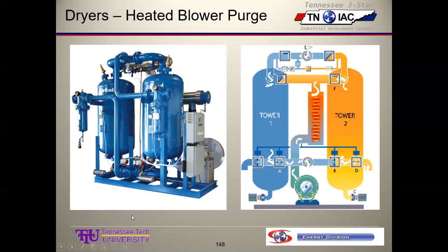Well, if you put that dew point sensing switching control in, it looks at when that dew point starts to creep up. It creeps up because the desiccant is saturated. Well, if it doesn't creep up, it doesn't regen. So it might sit there 10, 12, 14 hours without regenning. The other tank is dry and ready, but the tank that we're on is still good, so why switch them? And those controls are not that expensive. So that's one thing that we sometimes look at on energy studies.